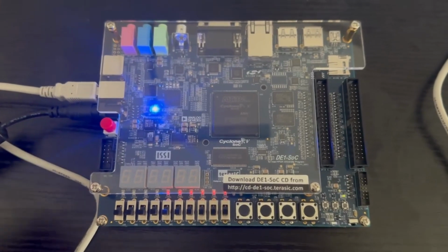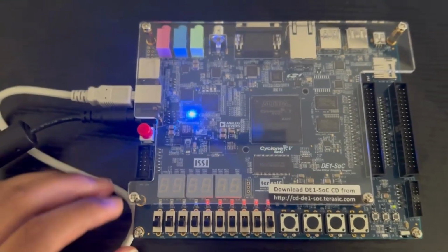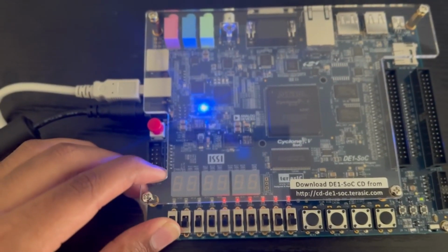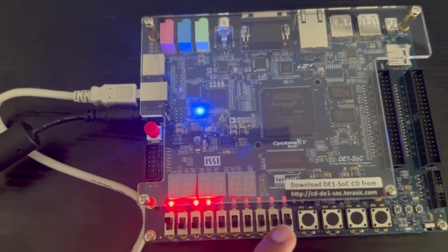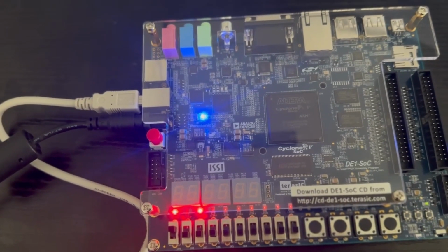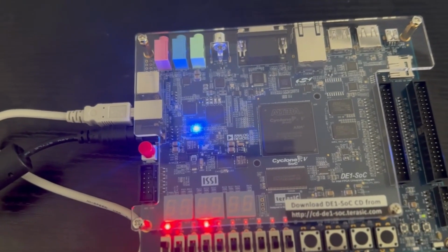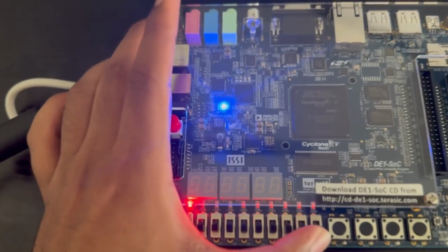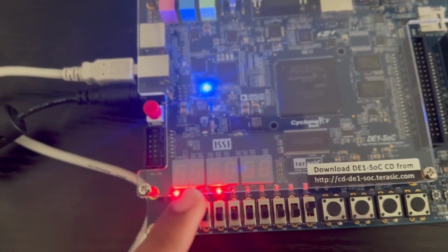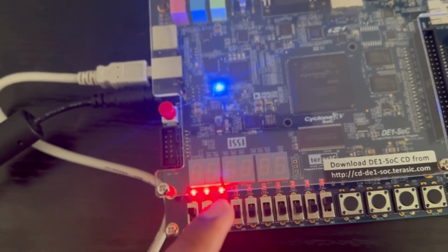As we can see, this is the FPGA board, and now this is the reset button and this is the direction button. Since the reset is active low, since I kept it at low, the top 4 bits are 0. As I release this, as you can see, since the direction is reverse, it will start counting down. See, as you can see, it's counting down, and then I'm going to increase the direction. As you can see, the counting up has begun. The four MSB bits are increasing, as you can see.